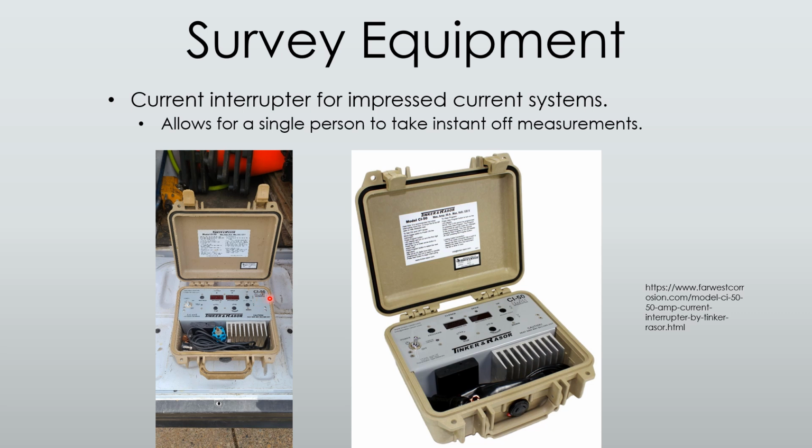So this is a current interrupter. This is the one I use, CI50 from Tinker and Razor. There's a lot of current interrupters out there. This is not the only one. You've got the program settings, the seconds on, seconds off. It's pretty nice. Set it, forget it. Basically, it acts as a light switch for the rectifier.